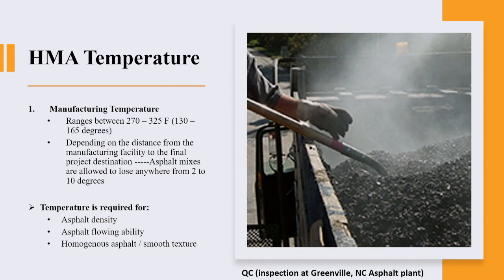You see that? By the way, we have the same story with RCC, roller compacted concrete, but it's not the temperature, it's the workability. Why? Well, temperature comes into play. In roller compacted concrete, as I mentioned earlier, it has to have 0 slump. So when you do the cone test, 0. So that means the concrete is very dry.